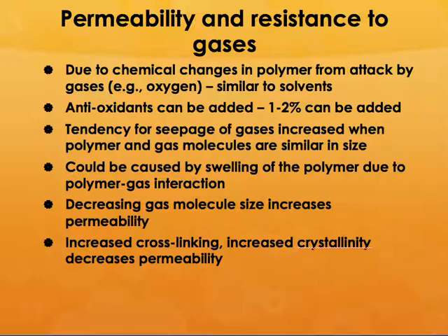And especially if the service conditions can cause some kind of a swelling of the polymer, then it can increase the polymer gas interaction. So as I said to you, if the gaseous molecule is extremely tiny or small, then it can increase the permeability of your composite.